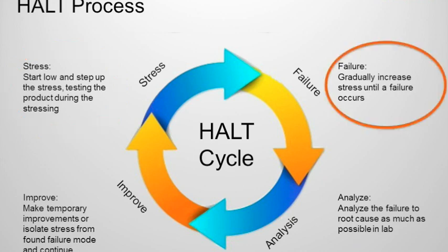Next, you want to make sure you're able to observe failure modes and performance variability. So you want to have the correct metrology on the product. You don't just want to be measuring the stresses you're putting in with accelerometers and temperature sensors.